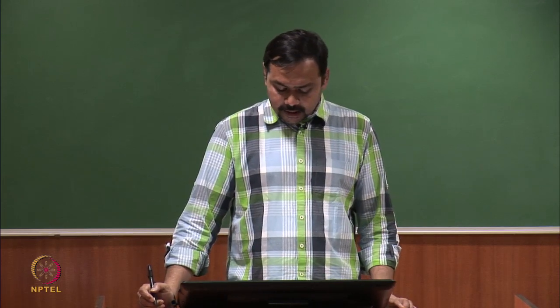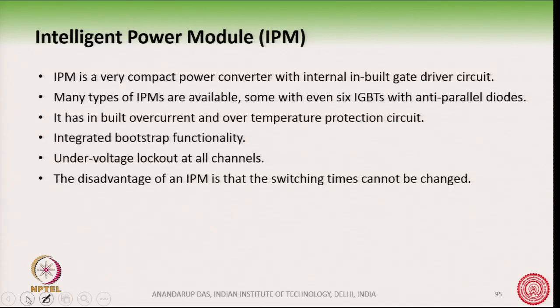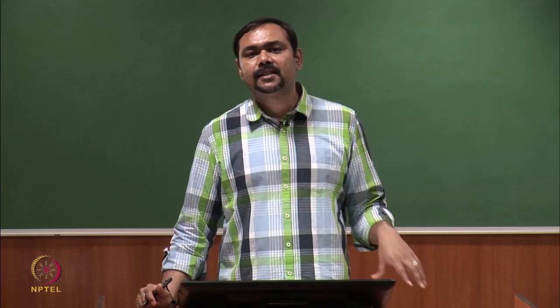Many types of IPMs are available, some with even 6 IGBTs and anti-parallel diodes. It has built-in overcurrent and over-temperature protection. It also has integrated bootstrap functionality and undervoltage lockout. So, many protective features are present in the IPM, and it is very compact in size.